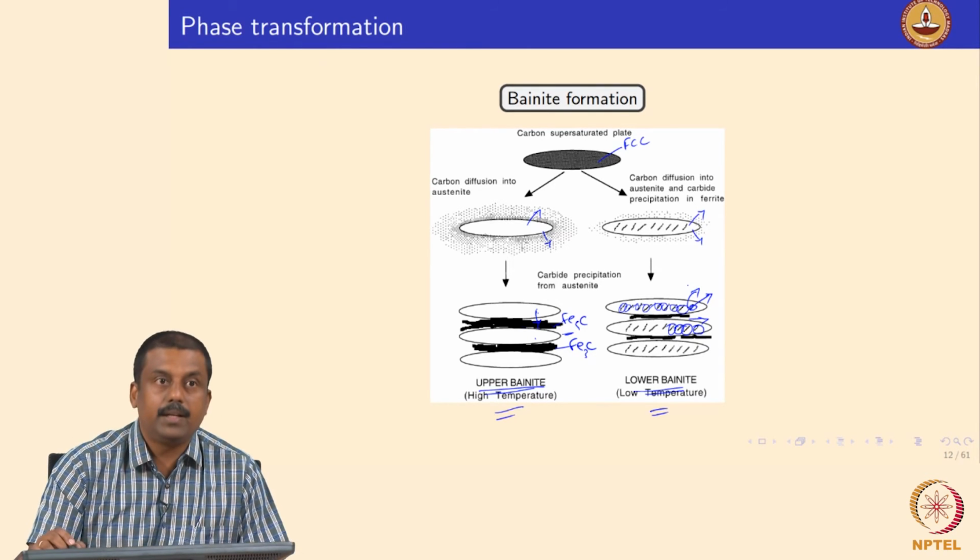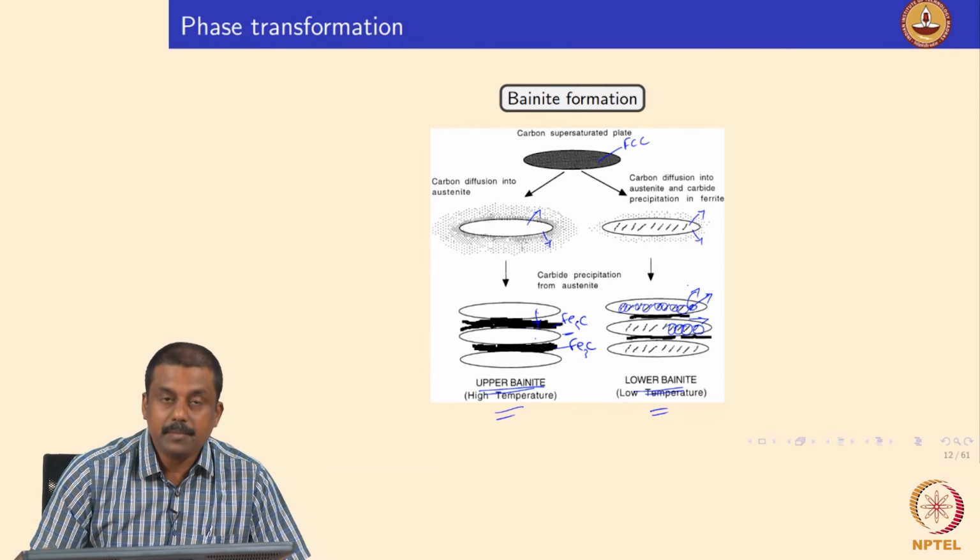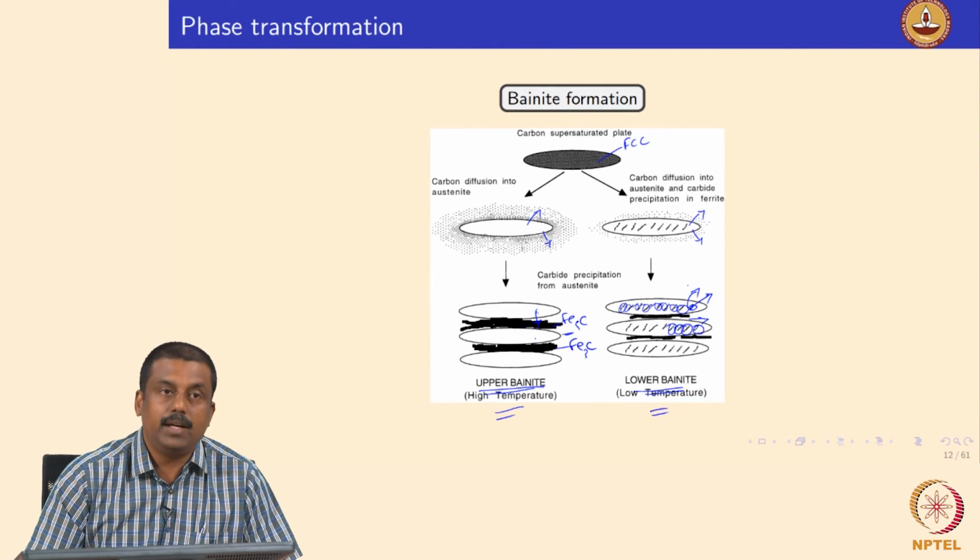Okay. So, with that we would like to summarize what you have learned so far. We looked at the basic iron-carbon system, the importance of the various lines you see in the phase diagrams, and the regions that are interesting for us in this course. We looked at the eutectoid composition, the carbon in austenite and carbon in ferrite lines. Okay. So, what are the possible phases that can form under equilibrium conditions when you cool, transforming austenite to room temperature.